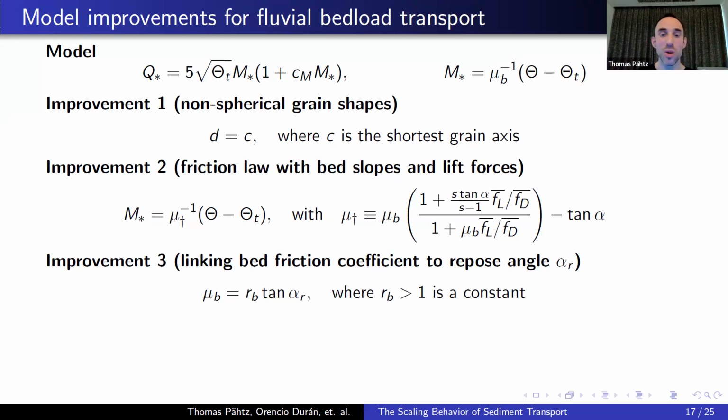Okay? So why proportional and not equal? Because we are talking about the bed surface, and the bed surface relative to the bulk of the granular material will have a higher shear resistance. And this is because when bedload transport occurs, you can think of it as the particles detaching from the bed, and they will find more stable resting places. And this is a process that goes on and on and on.